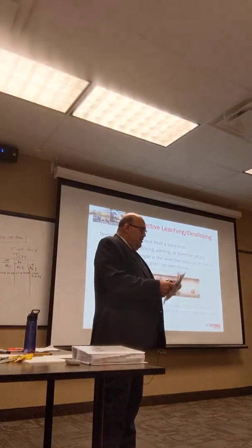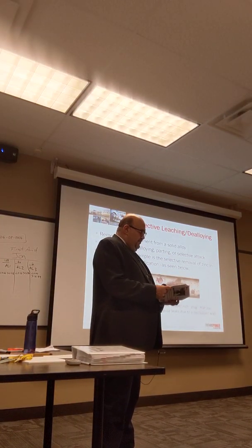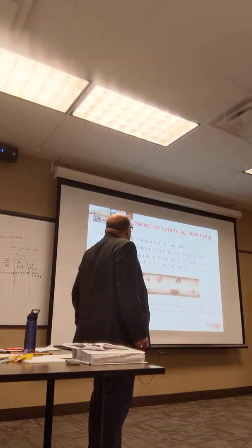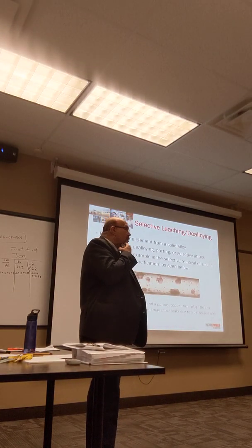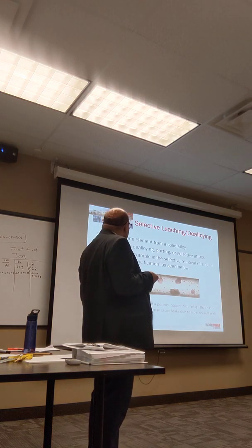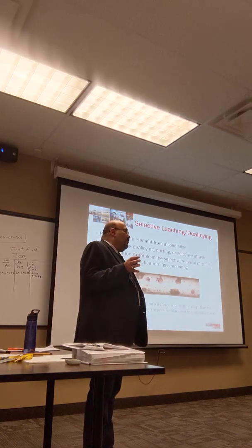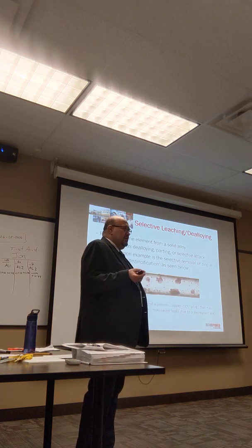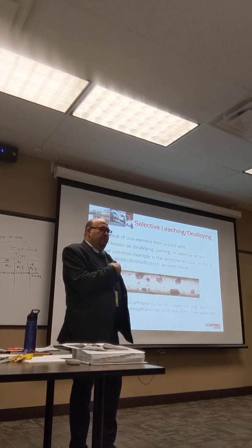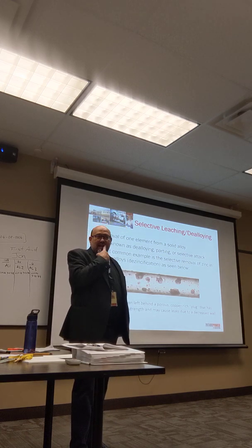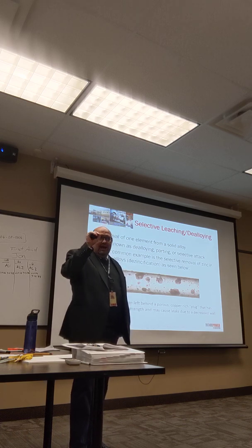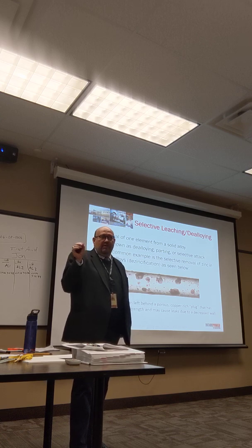Okay, so we're back, and this is the part about selective corrosion and selective leaching and de-alloying. So essentially it is the removal of one element in favor of the other one being protected. And as we saw from the previous slides, that can happen at the microscopic level, at the microstructure level. So certain phases can be attacked, and this is what causes the intergranular attack.